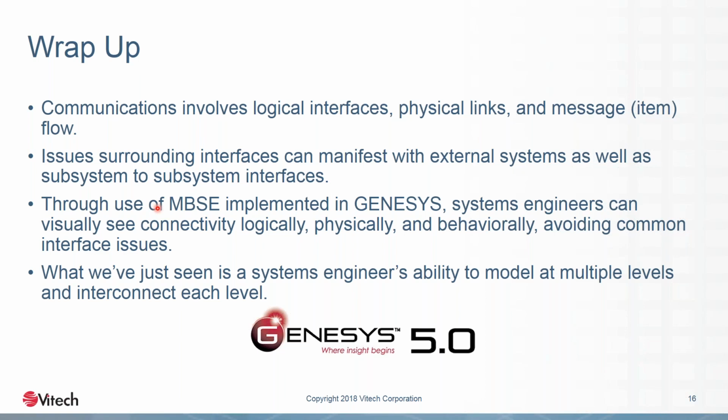Just as an example, in my background, at one point we were designing a system and we had settled on a parallel connection. Over time, there was a need to change it over to a serial, and what happened is one side made the transition to the serial connector. When we started to go to the next levels of detail at a CDR, we identified, oops, we have a problem because the transmitter is serial and the receiver is parallel.